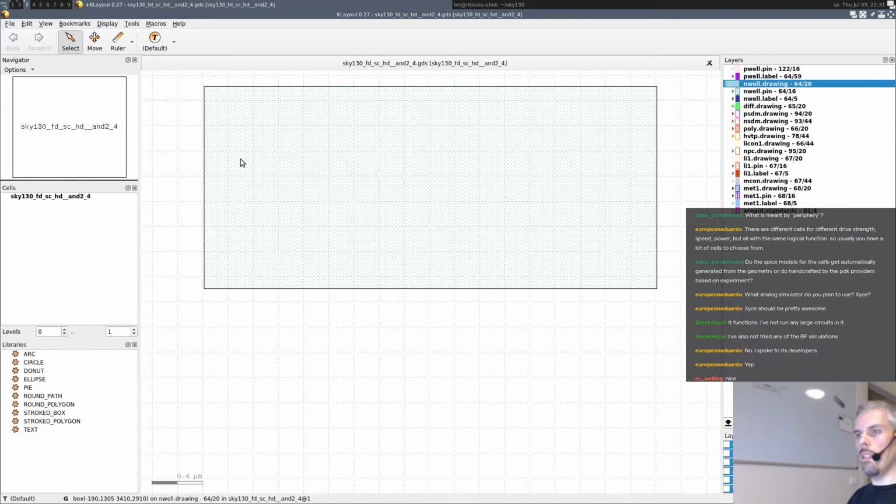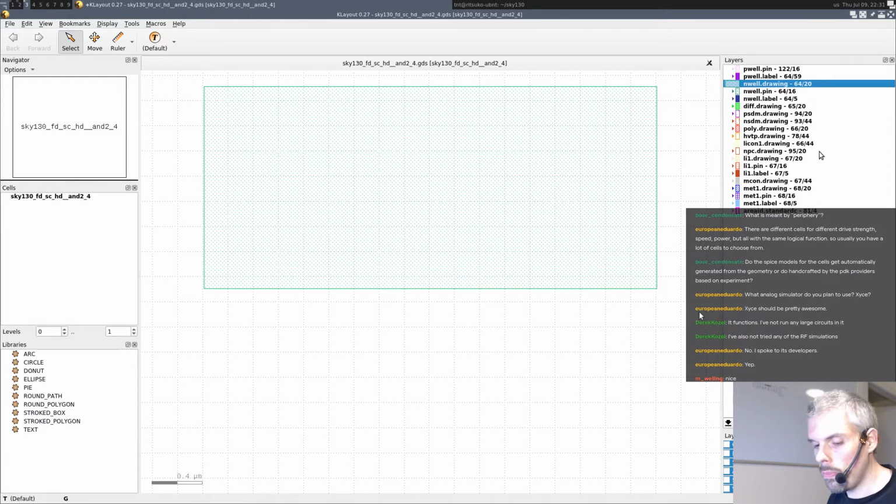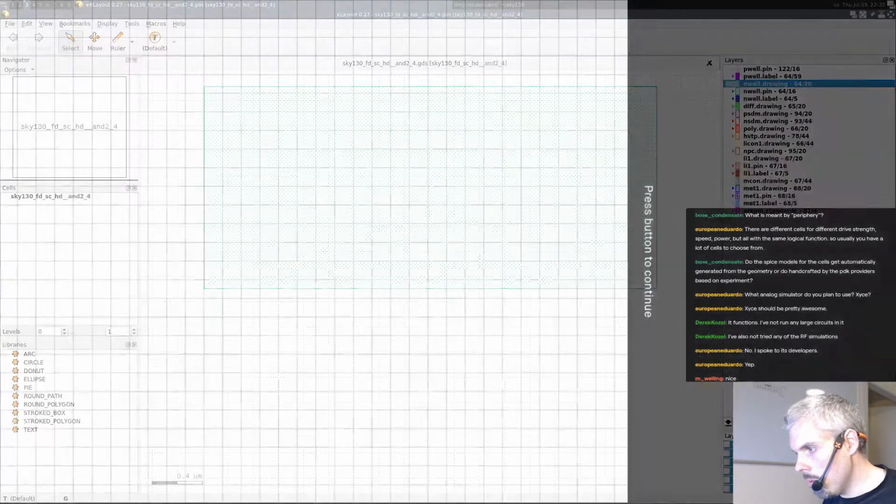And so you see, you remember the cell took the entire screen, and basically they put all the PMOS on the top and all the NMOS on the bottom. And so they just create a giant N well in which they're going to create the PMOS. Maybe I'll just quickly draw what the transistors actually look like, in case anyone isn't entirely up to date.